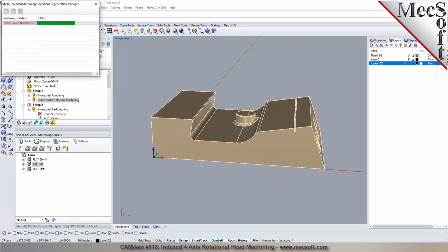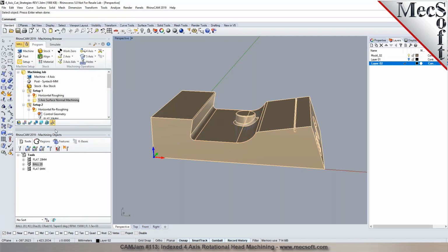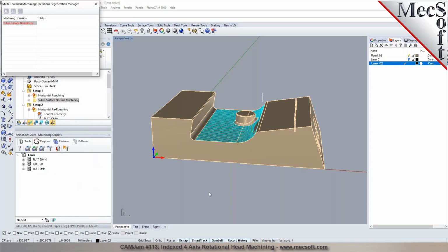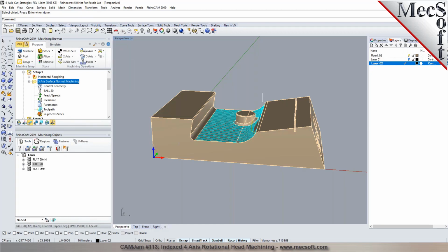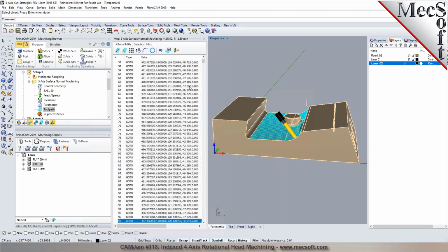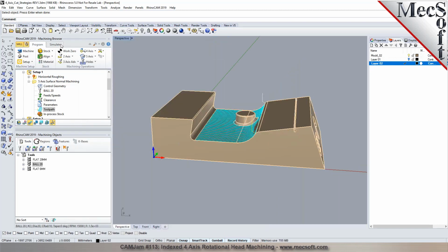So in this case, I'm not accounting for the features on the inside right here. So I can choose to lock it to 4-axis. And then generate the path. So you'll notice that the secondary axis angle is changing. You see -59, so it's constantly rotating. Your B is rotating as you're cutting it. So that would be in the Premium configuration.